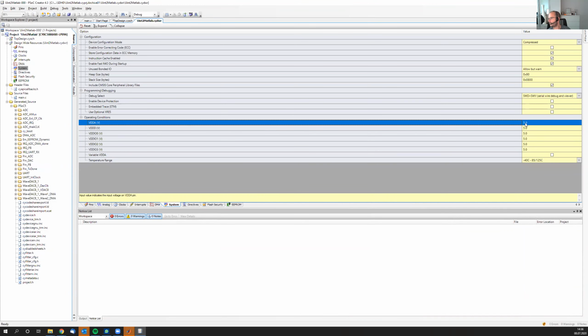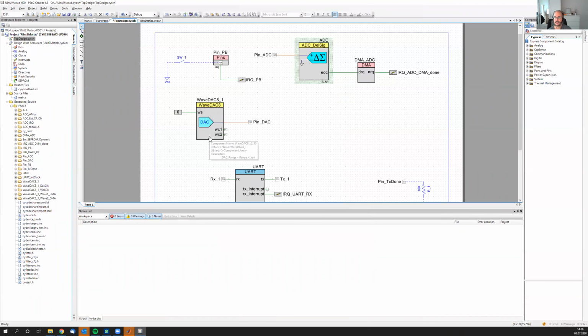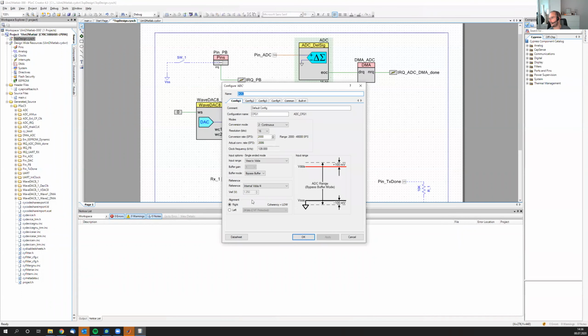And it's now defaulted to 5 volt because this is what we assume on USB, but the reality is a little different, and it might even vary from USB port to USB port. So actually you would have to measure it, or you would have to bring in an external reference voltage. This morning I had a small session with Mr. Hubrich, and he said that there is also somewhere an internal reference voltage we could use.